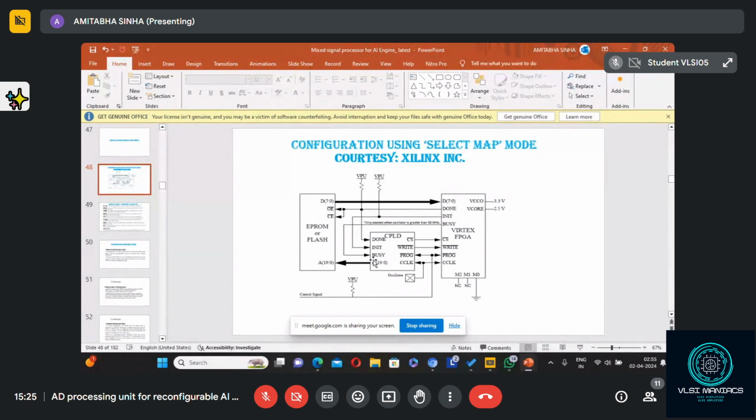In that way, the CPLD's address will become address plus 1, so again the next data will be downloaded. One after another, the data will be downloaded until the byte count register is set to 0. What is the byte counter? It tells how much data has to be transferred for a particular type of bit stream. That's all.